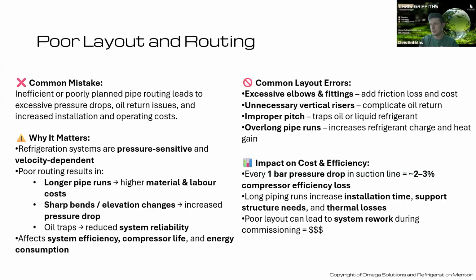It just makes sense. So why does it matter? Well, refrigeration systems are inherently pressure sensitive and velocity dependent, because both of those things, particularly on the suction pipe, will impact the efficiency of our compressors.